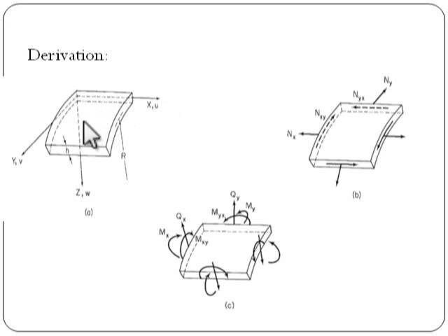Then y-axis is tangent to the circular arc and the z-axis is here, this one. The z-axis is this, which is normal to the median surface. Okay. Then here we will use the circumferential coordinate y instead of an angular coordinate, which facilitates comparison between the shell and the plate. So by considering the circumferential coordinate y, we can differentiate between plate and shell, which we will see in further equations.